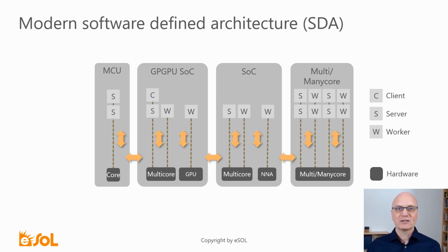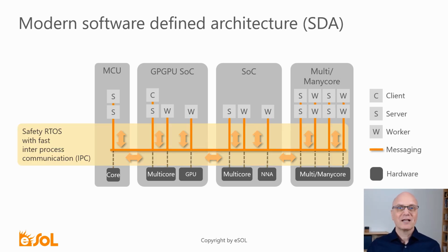For embedded applications, for example in a car with a speed of over 200 km per hour, at least in Germany, the system must be deterministic under all circumstances in order to avoid unforeseen conditions. A safety-certified real-time operating system, RTOS, must therefore be used. However, such an RTOS must be optimized for heterogeneous multicore and many-core chips, because this RTOS must enable the super-fast communication and at the same time maintain the deterministic behavior of the system.